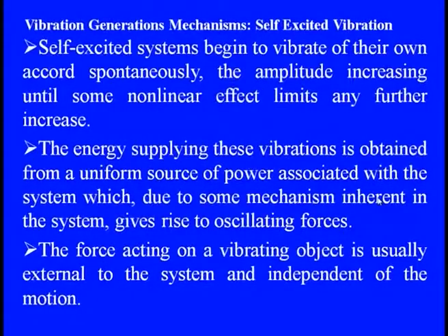The systems under self-excited vibrations begin to vibrate of their own accord, spontaneously, and the amplitude of these vibrations increases until some nonlinear effect limits it. So we can say that when a realistic system is rotating, nonlinearity is there.